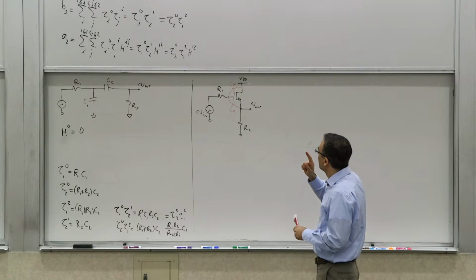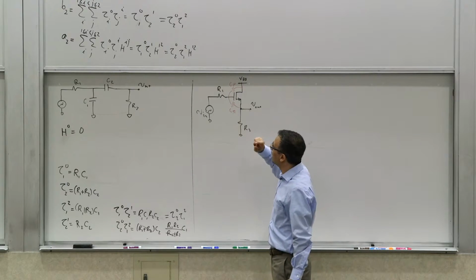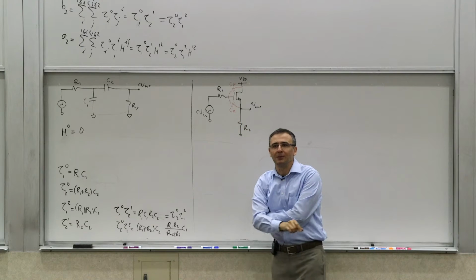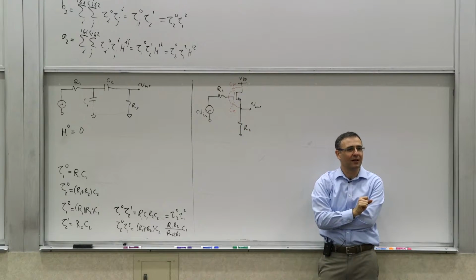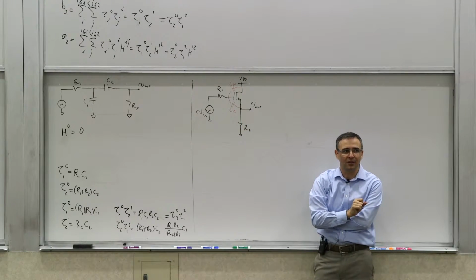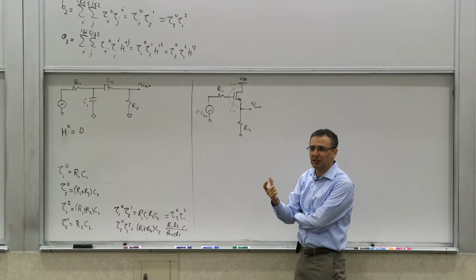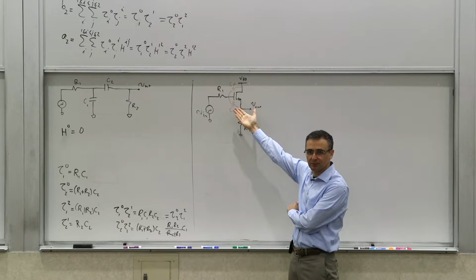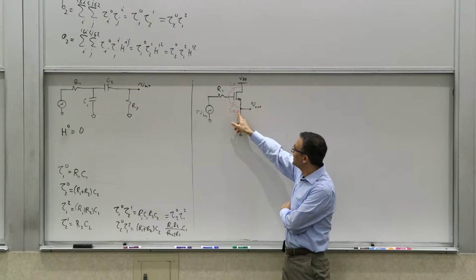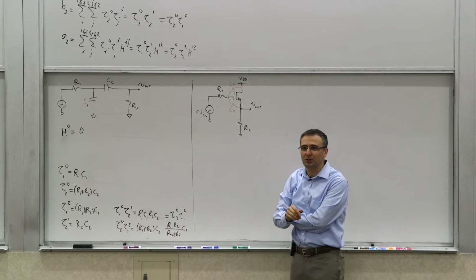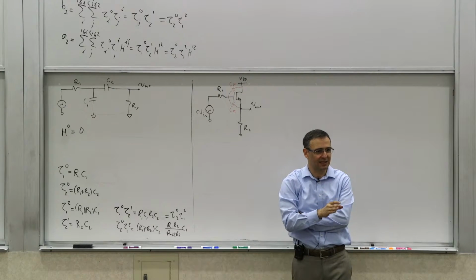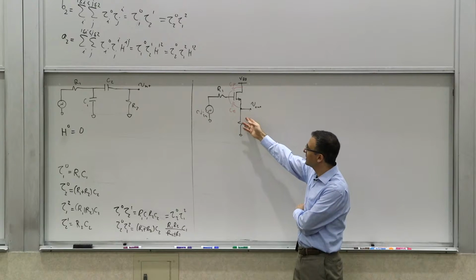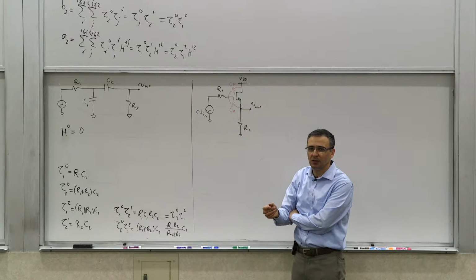Now, by the way, let's take a little kind of a detour. Where did this test come from? This test of how many poles, how many zeros, right? The pole, of course, is basically the number of time constants that would give you non-zero coefficient Bn, because it's the highest order. And what we did for the zero part, how did we do the zero? We said the maximum number of elements that can be simultaneously infinite valued, right? What is that number in this question?